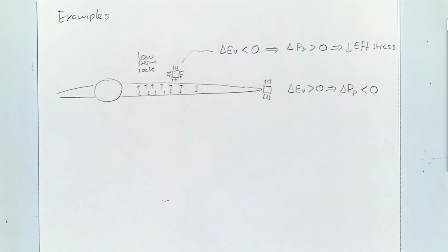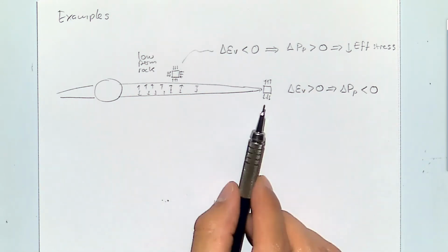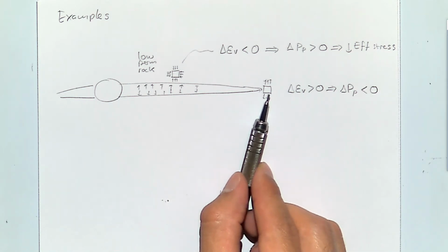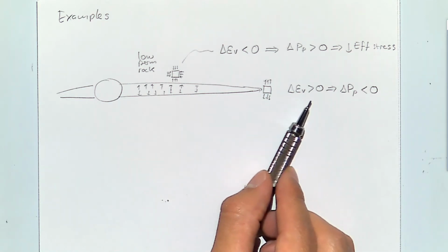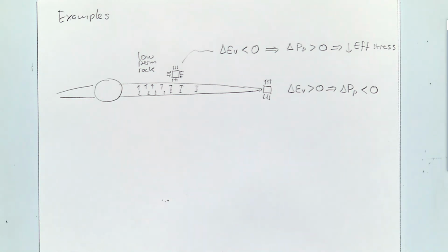But that doesn't make any sense, at least for absolute pressures. But I would expect in these cases that pore pressure may decrease at the tip of a fracture in an undrained process, because you are basically creating more porosity, and as you create more porosity, you need more fluid, and if this is undrained, that means that pressure has to go down.